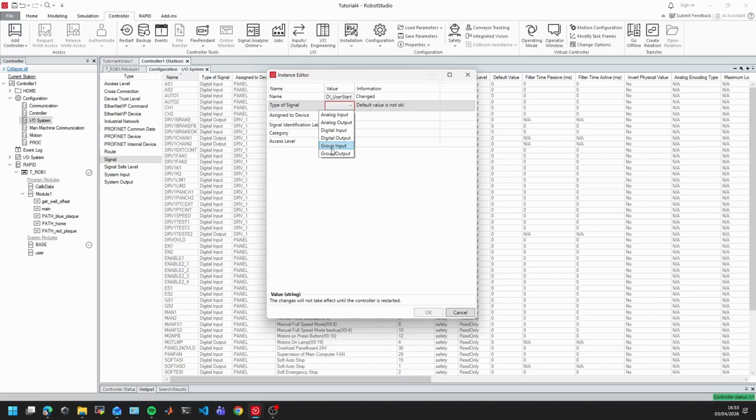So instead of using a network device, they just output a bunch of ones and zeros in the pins, and with that you send codes to other machines, or to other robotic manipulators, or to other PLC systems, so that they can communicate. Instead of sending one bit, you send a bunch of bits with different codes, to try to communicate amongst them. So that's why you have group inputs and group outputs.